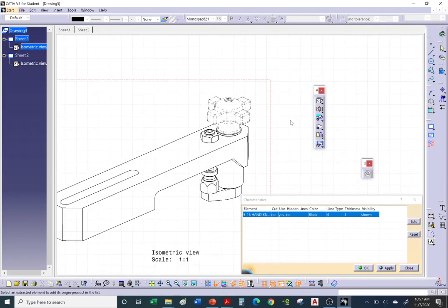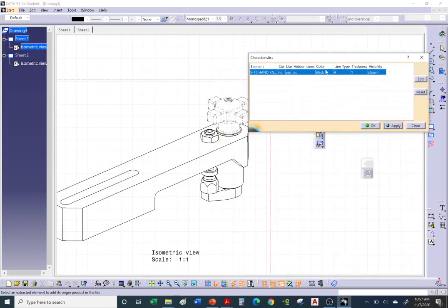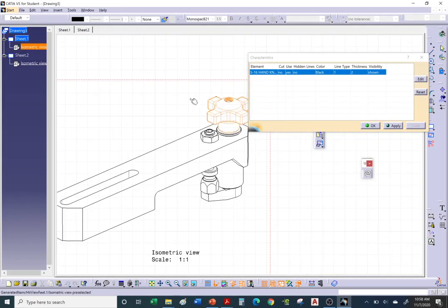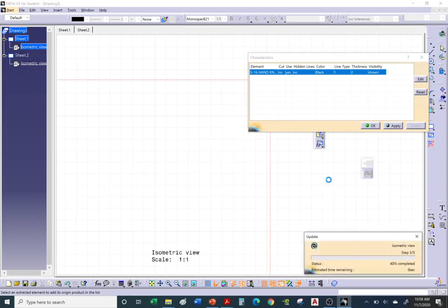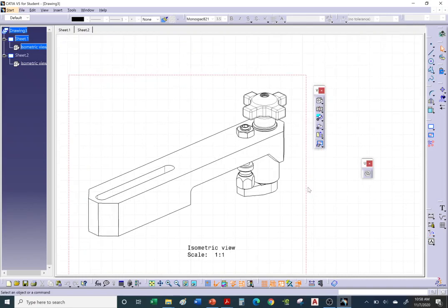As you can see, you can overload properties. You can always undo it. You can always reset. So you can always go back and reset it, select it from the list. You can do multiple items here if you like. We only have one. You can always reset the properties and apply, and it'll reset it back to the original. Okay, so that is overload properties. It comes in handy sometimes when you're dealing with complex assemblies and you want to at least give a preview of what it's going to look like on the next higher assembly drawing.